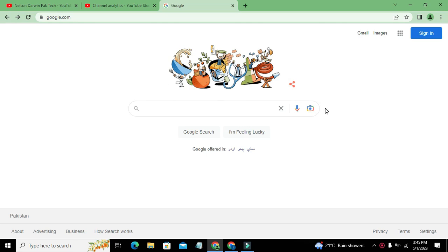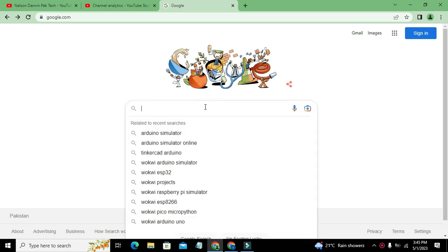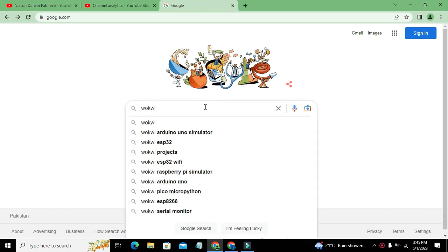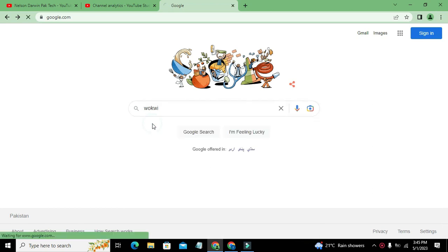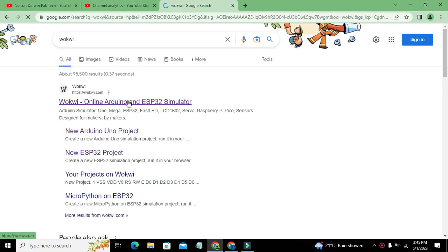Today in this video tutorial we will learn how to interface, or how to simulate, an ultrasonic distance finder, or ultrasonic sensor, with the ESP32. So how can we do that? First of all, we need to open Google and write Wokwi. Wokwi is actually an online simulator, so we need to click on wokwi.com.